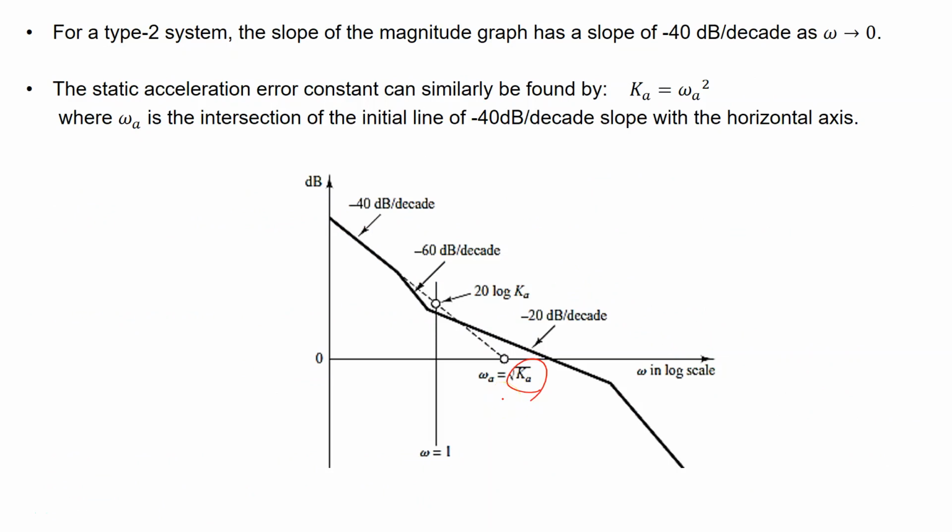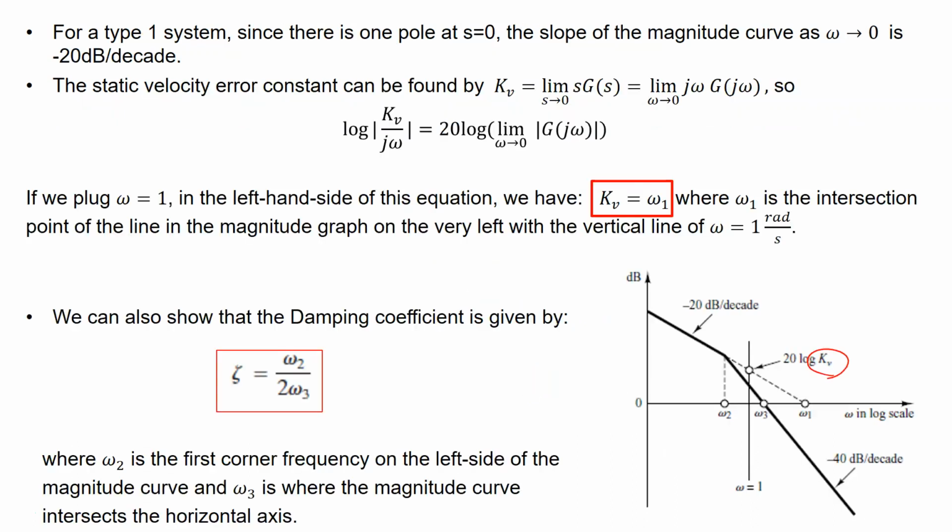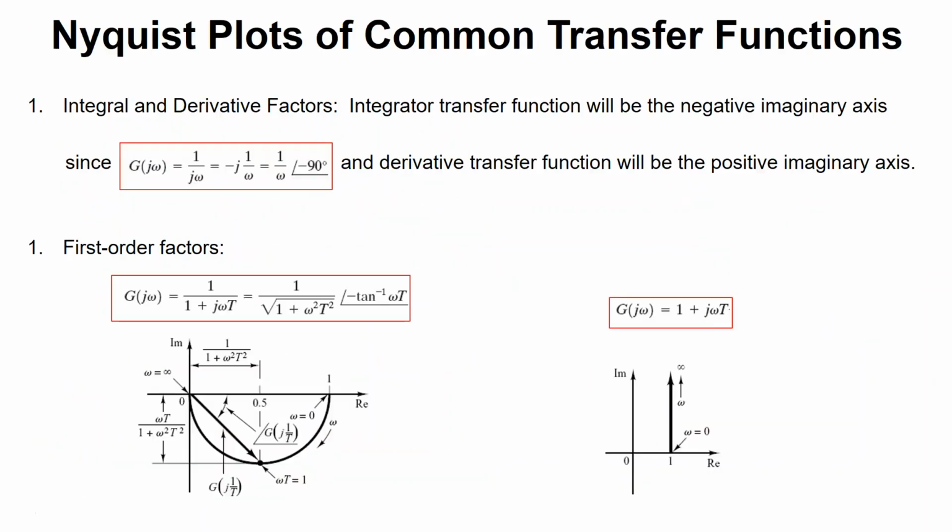Ka, Kp, and Kv are directly related to what? A steady state error. So yes, in the left side of my frequency responses, when omega goes to 0, that's where I can talk about steady state error. And then what can you find in the mid-range?